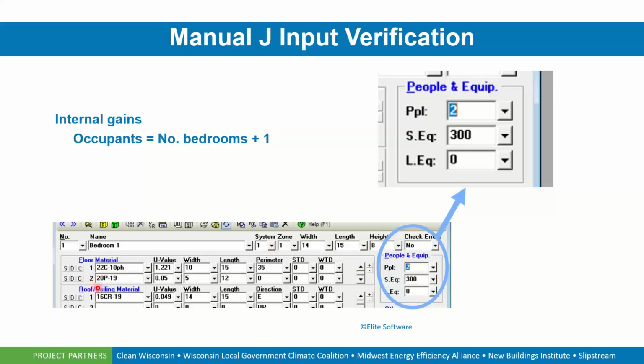And we add in our requirements, our building components. So this looks like it has floor over an area. Excuse me. We have floor insulation. We also have ceiling insulation. So this is just a partial screenshot. But we would have walls and then our fenestration or our glazing and our doors, exterior glazing and doors, on down below within the software. And you would assign that to a particular wall and assign orientation by wall based on the plan set.